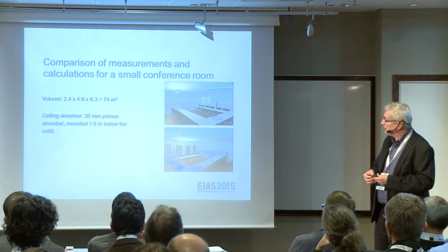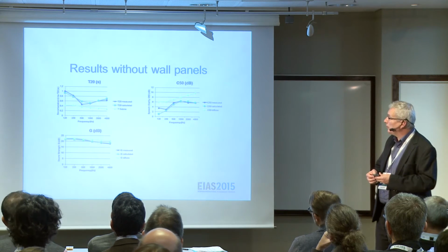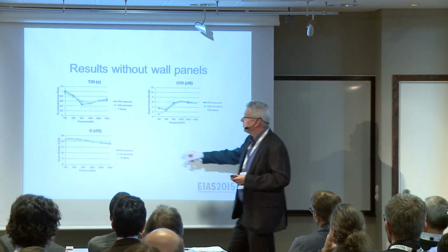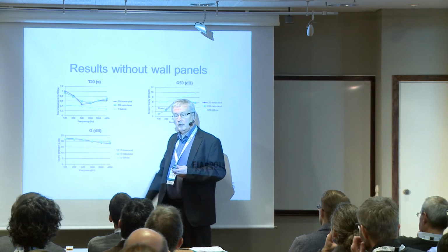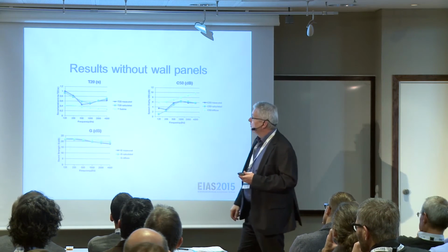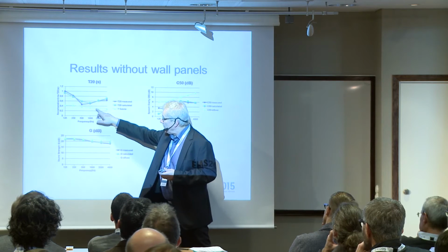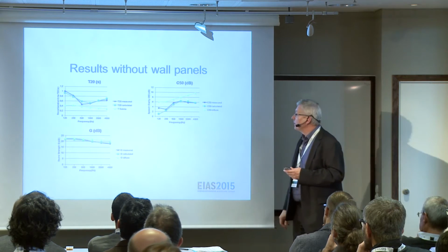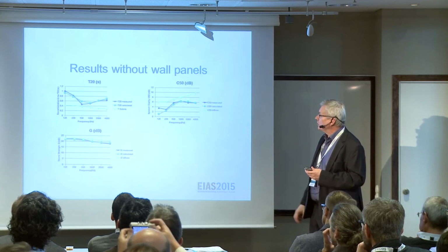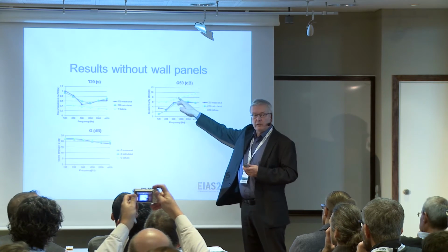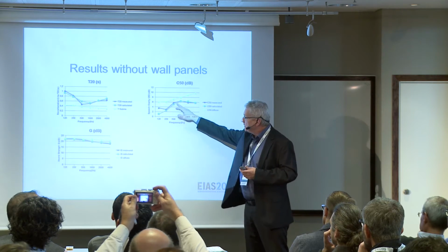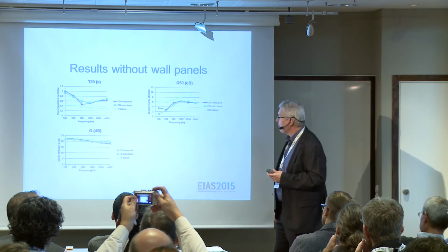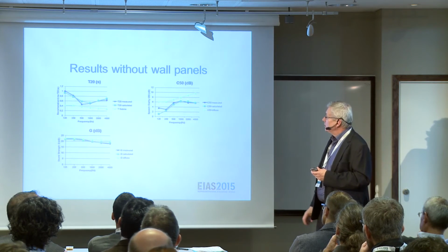I can show you the results here. This is without wall panels, and you can see this is quite good correspondence. And of course, this very much depends on that I use the scattering measured in these rooms. You can also see that the reverberation time by Sabine is quite low, and you see the diffuse field theory gives another shape. But the frequency dependence in these models is more correct. So this is quite okay.